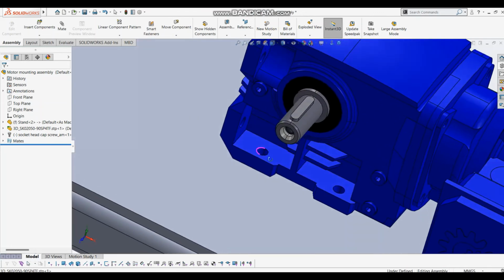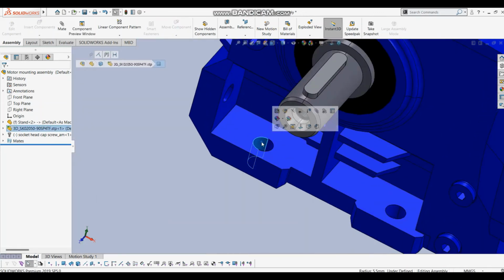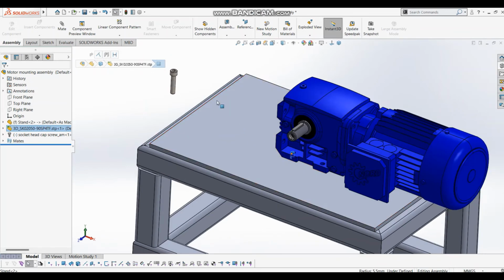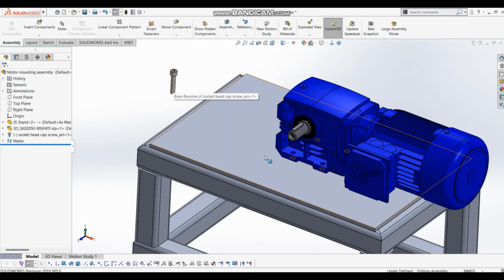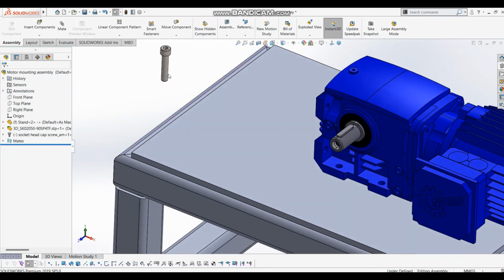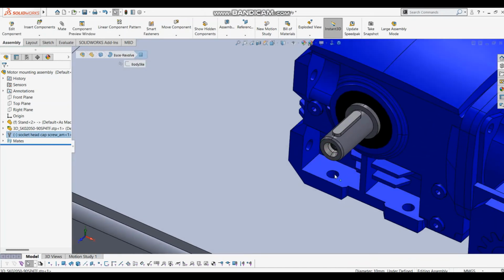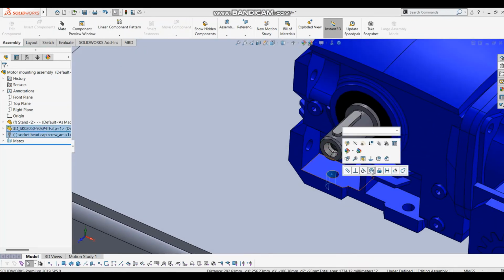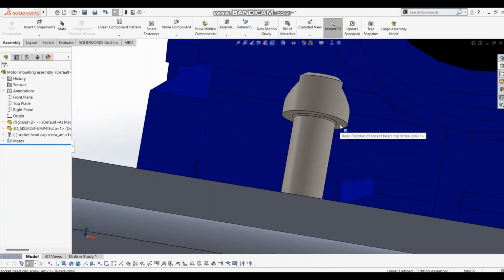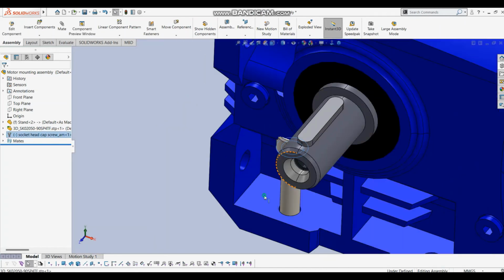And let's check the size. This size is 5.5, so that will be 11 size for that hole, and then the M10 socket screw will suit there, is suitable. Let us give the constraints: circular constraint, concentric constraint, then flat face.